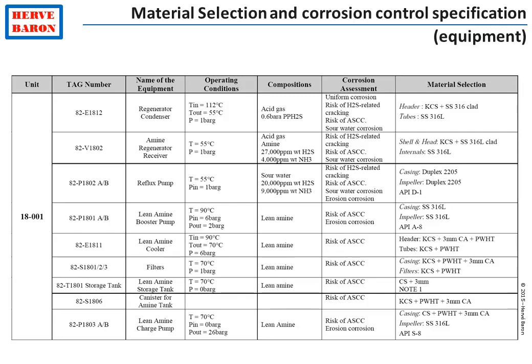Besides the wall thickness thinning phenomenon that we discussed, another type of corrosion is very common in oil and gas facilities. It is called cracking corrosion. The most common one is the one induced by hydrogen sulfide. Hydrogen sulfide, in presence of liquid water, creates what is called sour service. In sour service, there is a risk of cracking of carbon steel.